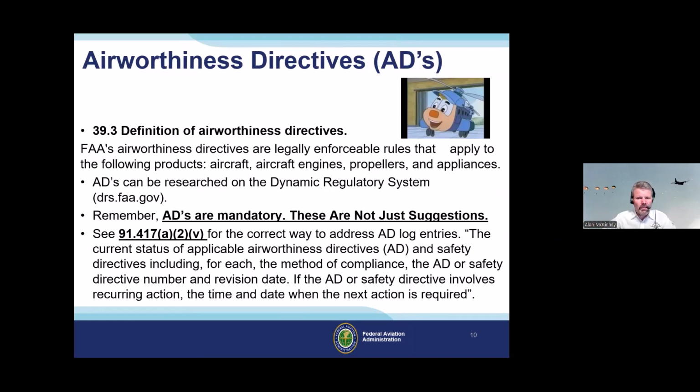Let's talk a little bit about our airworthiness directives. I don't want to beat this horse to death too much because I think most folks are clear on airworthiness directives. They are mandatory. Again, this says they're not suggestions. They're not. They are enforceable rules. In an AD, it will have what it's applicable to or affects. So it will cover make, model, maybe serial number, what it is, what serial range or part numbers. It might be a one-time or recurring AD.